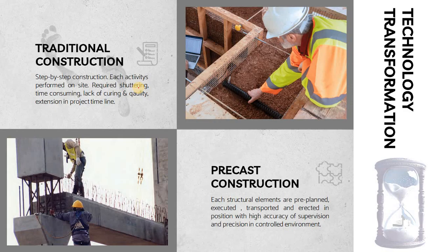On the bottom left figure you can see the beauty of the precast, in which the precast column is erected above one of the columns. These are the dowel bars that are projected from the below column, and then this is another column that will be connected with the bottom column, in which there will be a tube, or a hollow section, in which the steel will be connected through this dowel tube, and then the dowel tube will be grouted with the cementitious grout to connect these two columns together.